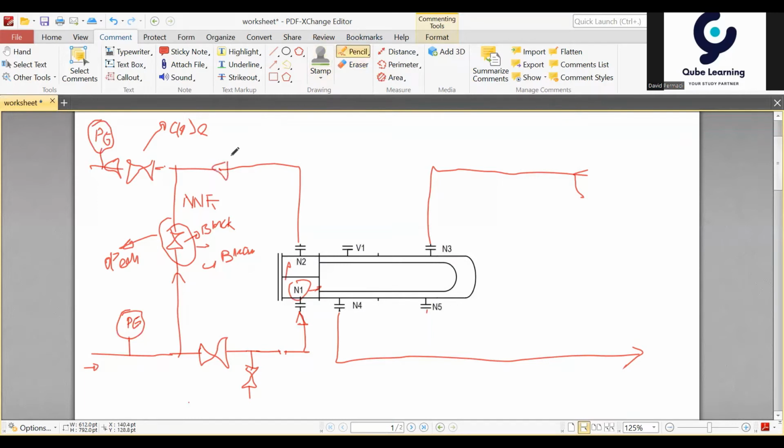because the heat exchange is also driven by the temperature gradient. Okay, do I install a TI here or a TG? The TI is much more expensive than the TG, and because it's just cooling water, I need to consider just the TG. So we can see if there is an abnormal situation inside of this exchanger.